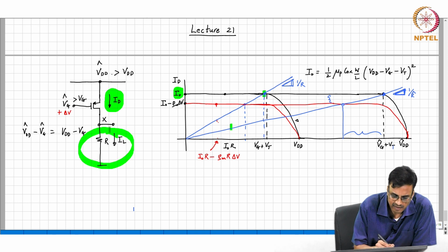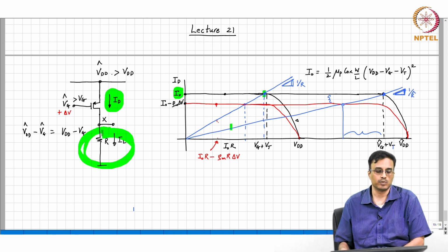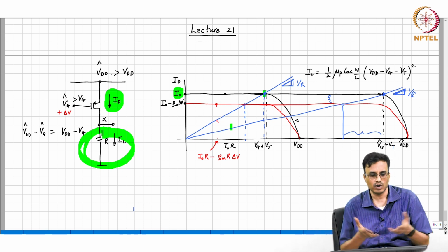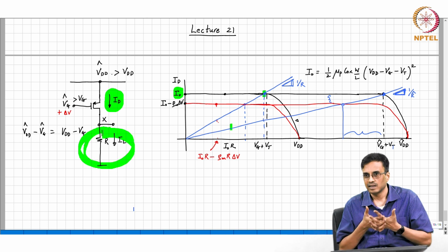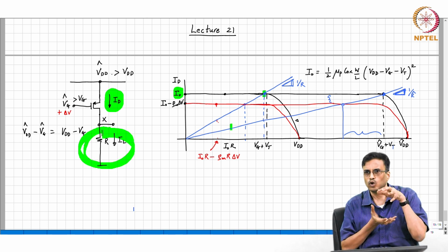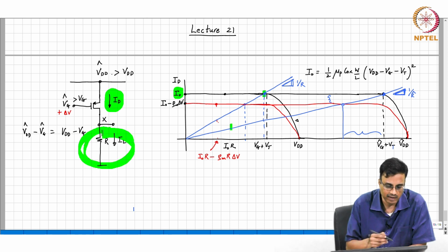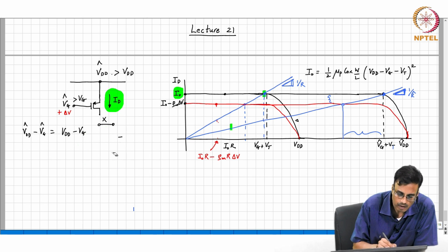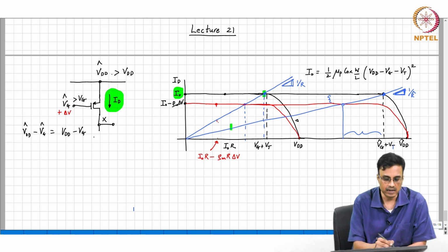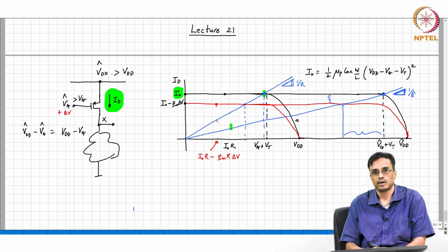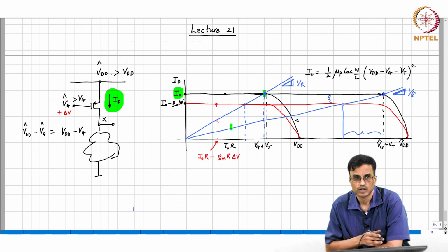And further, what kind of element is a resistor? Is it passive or active? It's passive, because there is no energy source inside. So, whatever we replace there must also have no energy source inside, okay. So, we would like to replace it by something else, so that the incremental gain is very large, okay, even with a small VDD.